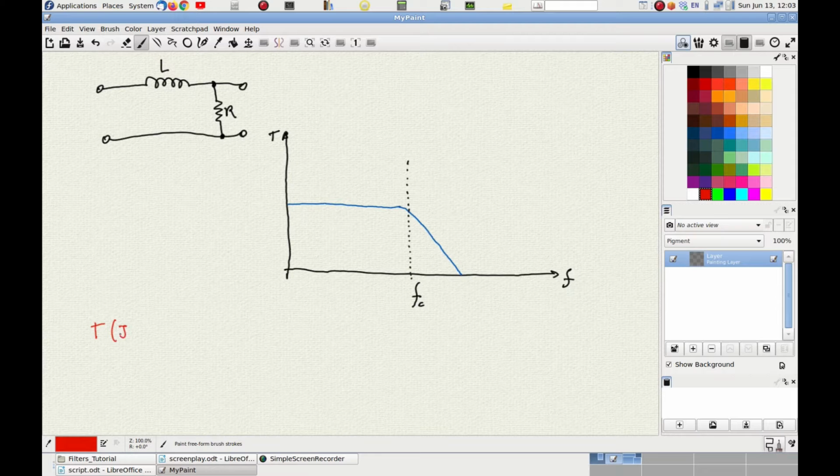And, in fact, if you think about it, at the lowest frequencies the inductor behaves just like a resistor of very low value, practically 0 ohms, and so the voltage divider composed by it and the resistor R brings the total amount of voltage present at the input exactly equal to the output.